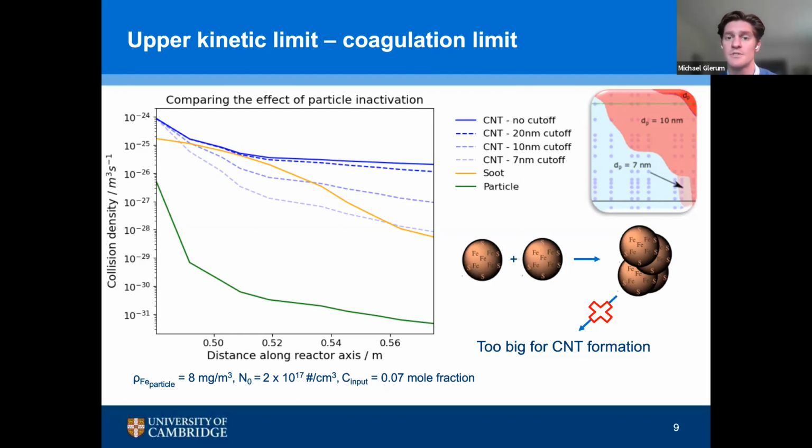If you take that and realize that I can only put in a specific amount of mass into my synthesis process, after that your catalyst will grow far too big and inactivate itself, and you're unable to form the carbon nanotube particles. So this graph describes what would happen if you endlessly push that boundary. You would start to hit that upper limit and effectively render your catalyst useless, and it will crash out into your product, meaning there is a specific amount of methane that you are able to process with this floating catalyst CVD synthesis.